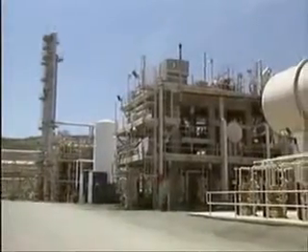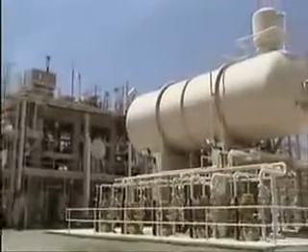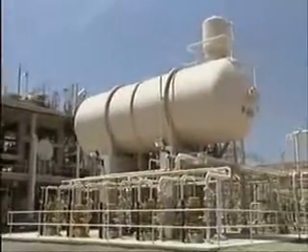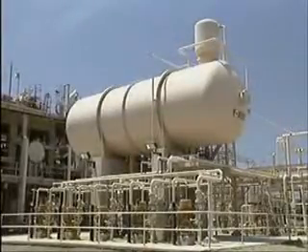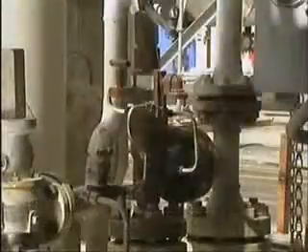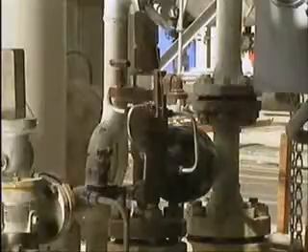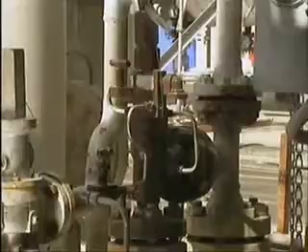valve repairs. You see, by law, safety valves can't be isolated from the systems that they protect because of the damage that could occur if the systems were operated without protection. So, whenever a safety valve is damaged, its system must be shut down while repairs are made. Pilot-actuated relief valves, however, can be isolated from a system because they're not a primary part of the system safeguards. So the pilot-actuated relief valves can be used and then repaired if necessary without having to shut down the system.